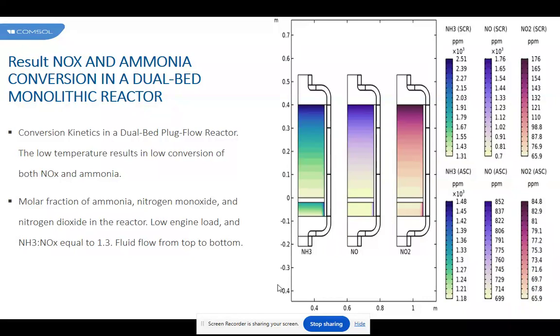According to the results, a difference of 40% in apparent permeability is sufficient to lead to a large mass flow distribution, which impacts conversion efficiency and pressure drop. The two mentioned variables show a positive or negative correlation depending on which part of the substrate, core or ring, has the highest permeability. These and other results contribute relevant evidence for further monolith optimization.